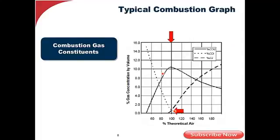If we look right here where this red arrow is and my little red dot, right here is 100% combustion efficiency, stoichiometric combustion. I've got no excess air on here. I've got no CO. I'm burning everything. That's stoichiometric combustion. But the way we set these burners up is to go air on the right side of the curve in order to give us that margin of air. So we don't go fuel rich and have a post-combustion explosion in our furnace.